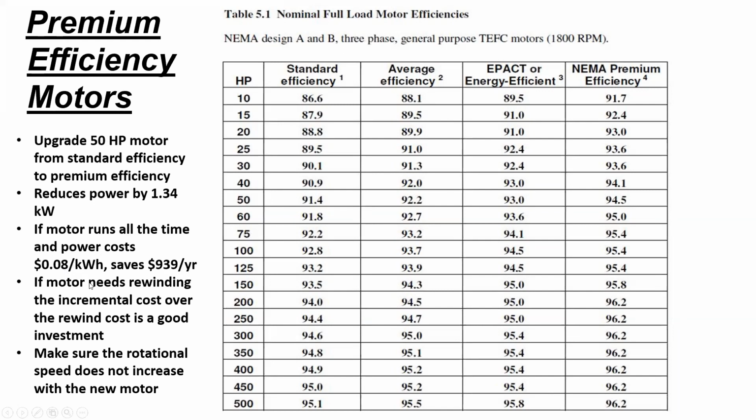On the other hand, another option would be rewinding. If it breaks down, we can have it rewound. Of course, we're probably going to lose some efficiency, some points. So one study could be: is it worth losing some points of efficiency, in case we're using it that long, or are we better off upgrading to a more efficient motor and saving energy that way?